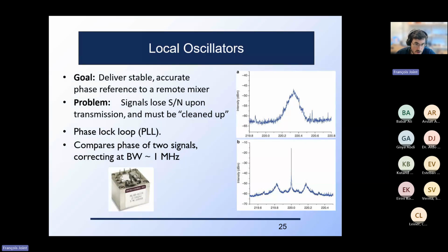So the importance of the LO is to be extremely pure and extremely stable. So we need a locking mechanism and also a filtering system in order to get a very pure and controlled single mode frequency, basically. So it's a lot of metrology that comes from this generation. Mostly it's using Schottky diodes that allow this multiplication.